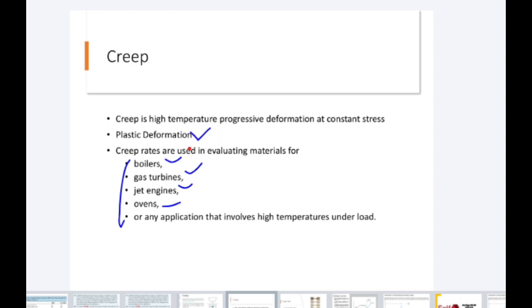Questions will come from within the slides. Because you people don't focus, if tomorrow I put a question asking whether creep is plastic or elastic, most of you will say it is elastic, because you don't read the slide and you don't listen. Why is it plastic? You have seen it in the experiment. The material breaks, and even if you don't break it, we see plastic deformation, meaning the material cannot come back to its position. We don't stop it, right? Because we perform the experiment until fracture.